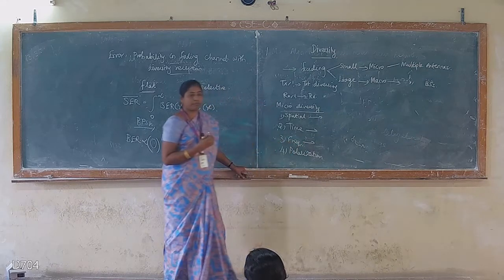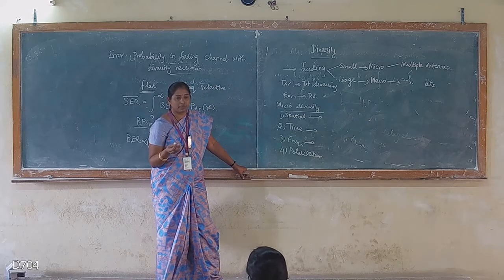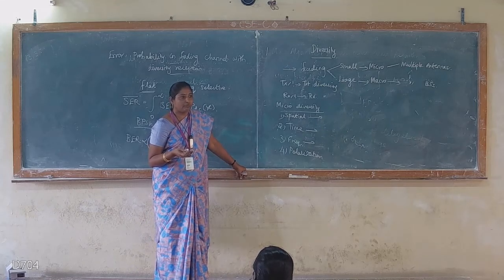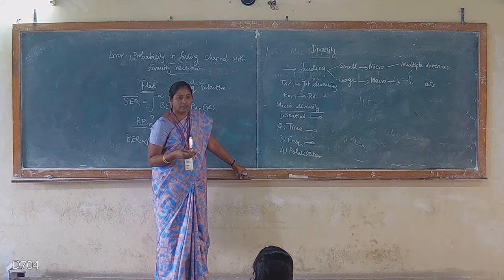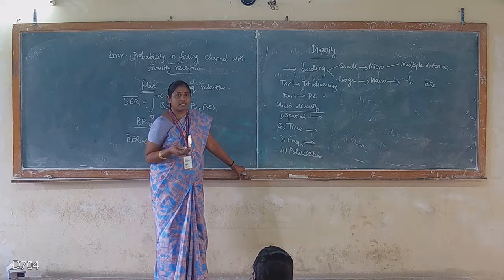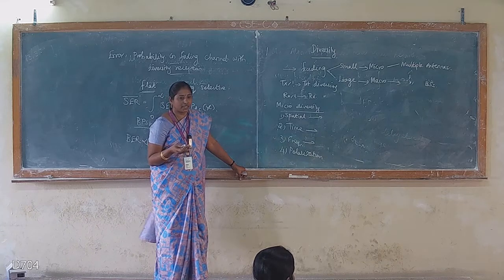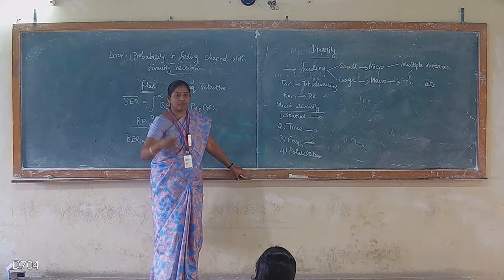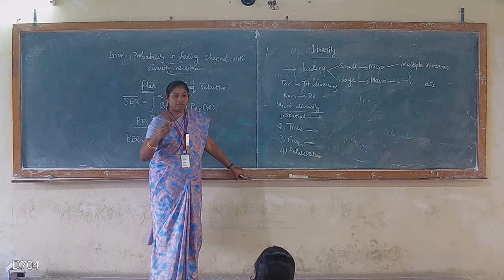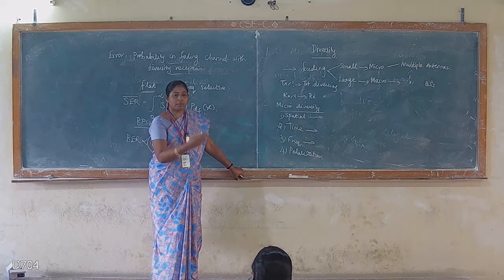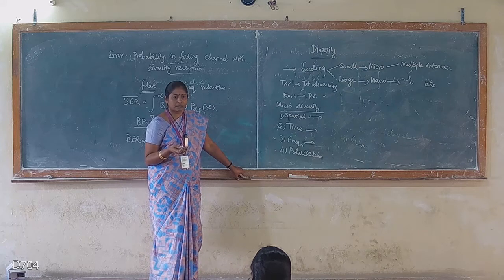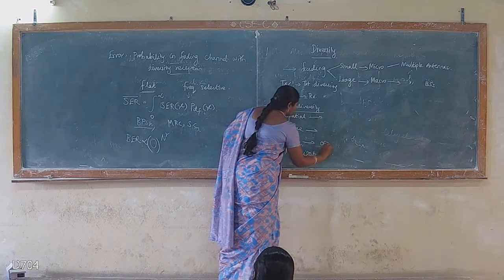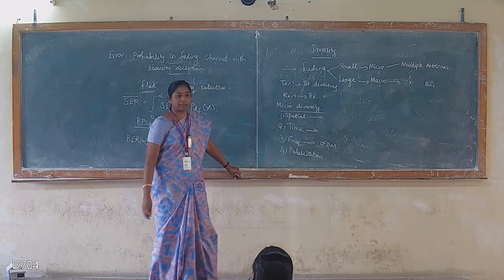Frequency diversity, how do you implement? Same information we have to transmit at different frequency. If you are transmitting the same information over different frequency, what about the spectral efficiency? That is very poor. Okay, because all the frequencies carry the same information. So the spectral efficiency is very poor. So what we are doing is, instead of transmitting the entire information over different frequency, we have to split the information into smaller parts. Then every smaller part is transmitted over one frequency. Okay, that is also applicable in frequency diversity. The best example of frequency diversity is OFDM. Okay, so the same principle we are applying in OFDM.